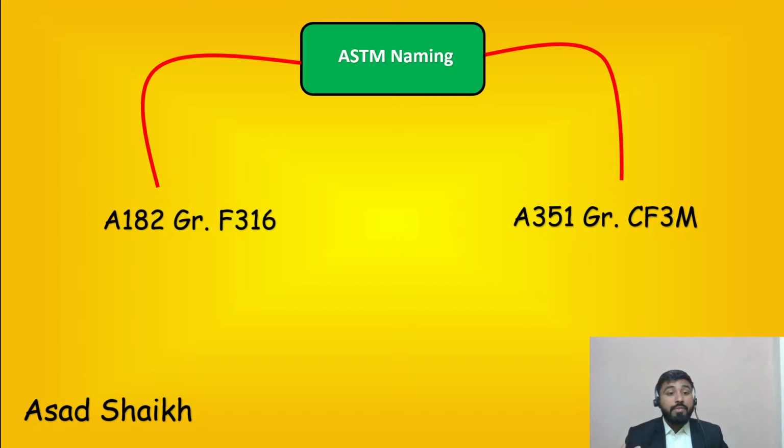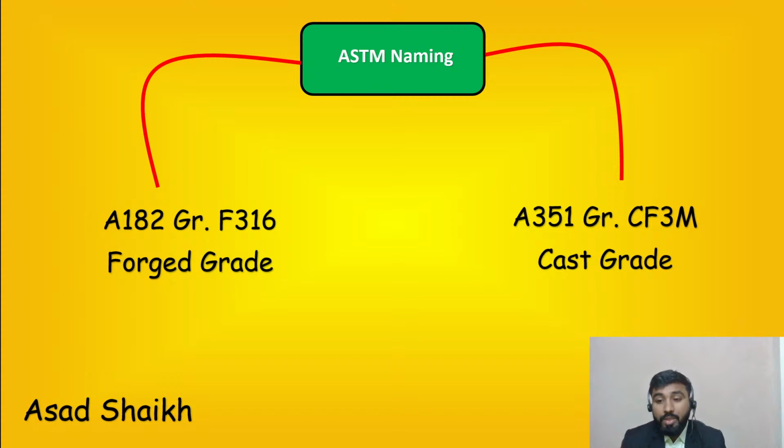If the vendor gives you the UNS numbering system of the material, you don't know whether it is a cast grade or a forged grade. And I'm talking about world-renowned companies that could reject by saying no, they want the forged grade, and that is what is specified in their specifications. So be very cautious of this point as well, and that is the reason why I put this here. Both of these stand for nothing but 316, but are different grades.